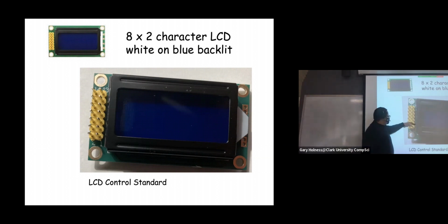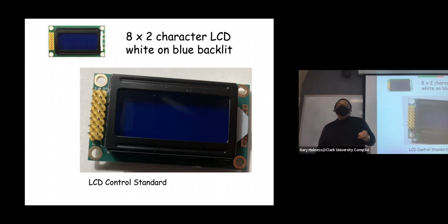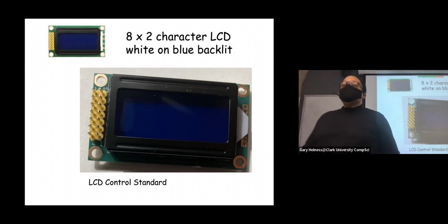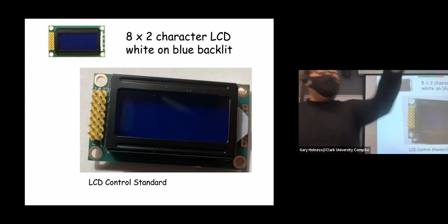And if we imagine these pins as consisting, and there are a total of 14 of them, of 7 rows going across and 2 columns, we number the pins when we count them row major from right to left. So this is pin 1, that's pin 2, 3, 4, 5, 6, etc., up to 14. And so this right-hand column, on your right, is all of the odd numbered pins: 1, 3, 5, 7, 9, 11, 13. And this left-hand column, on your left, are all the even numbered pins, 2, 4, 6, 8, up through 14. Any questions about this? Make sense? Yes.